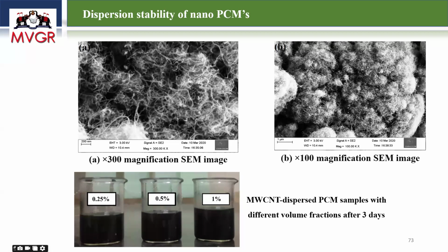I mixed three compositions: 0.25%, 0.5% and 1%. These materials I kept in the liquid state for a period of 3 days. Above the melting point temperature, even after 3 days, the nanoparticles are not sedimented. It is still well mixed in the phase change material.